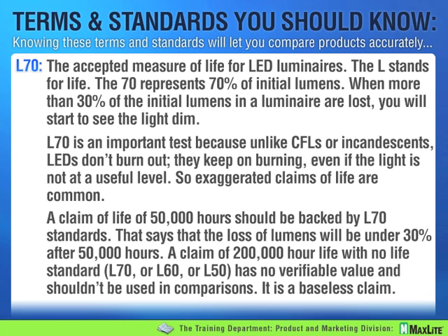Now here's the meat of our presentation today, some terms that you really need to understand. I've got some issues coming from the field almost every day where people misunderstand literature and say, oh, your fixture dies at 50,000 hours. Let's talk about how we define life for LED versus traditional light sources. Real quick background on traditional light sources. The life is measured very simply in about half the world, where we light up 100 bulbs. When the 51st one fails, you round it off, and that's the stated life. That's been an industry standard for over 100 years.